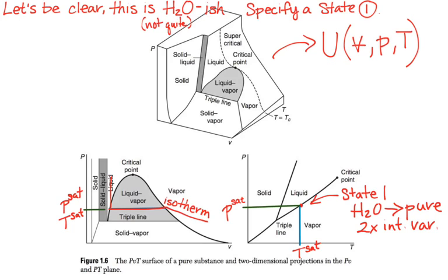Underneath that vapor dome, that little horizontal tie line, that is where Psat and Tsat are defined. So even though temperature is not explicitly defined, it is constant under the vapor dome there. And I have my two points, my two end members along that tie line, between the vapor dome left side and the vapor dome right side. That would be my saturated molar volume of the liquid on the left, and saturated molar volume of my vapor on the right. Again, same temperature, different molar volume of liquid versus molar volume of vapor.